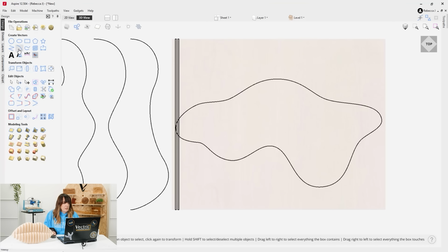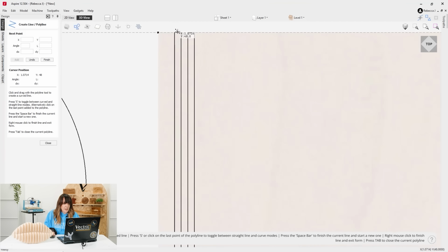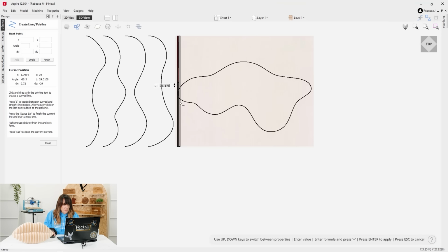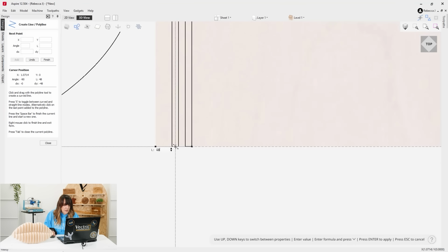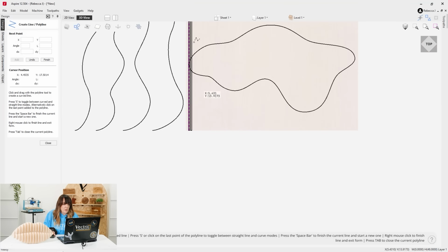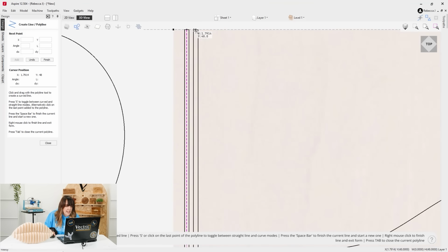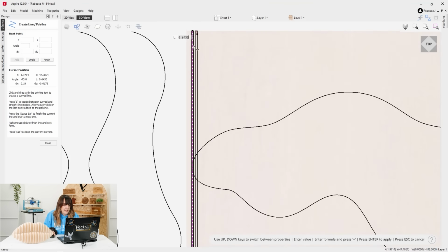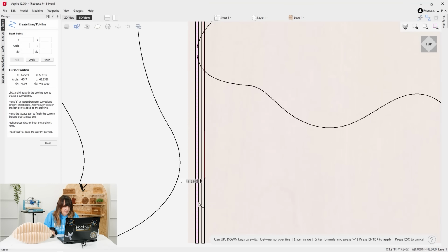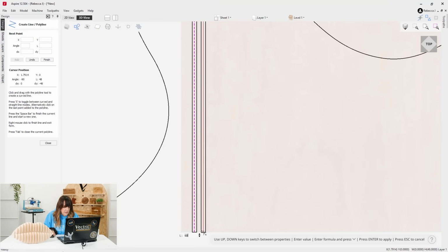And then I'm going to look at drawing a center line between the top and the bottom of the rectangle. The reason for that is this will give me a good midway point of where we've split up that component, and I can use this vector to line up my profiles when I come to look at other tools that will help me do that. So we'll just press space to accept that, and then we'll go up to the top here and do the same over here. So snap to the top there, and then we're just going to come over here and snap to the bottom there.